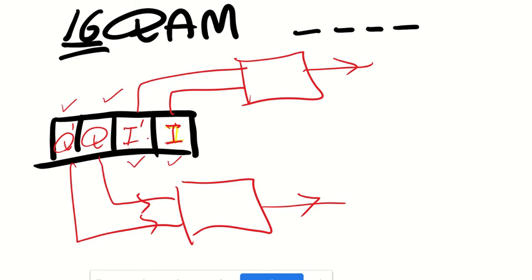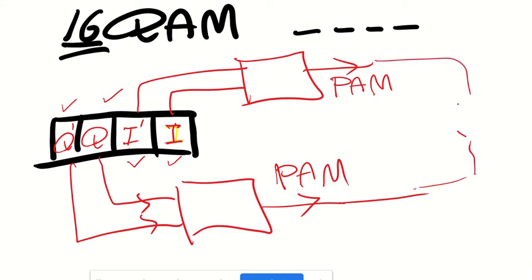Of these 2 bits of information, one bit will change the amplitude, the other bit will change the phase. What comes out is phase amplitude modulation. They get mixed, and then they are sent to transfer my data. So it's a very smart way.